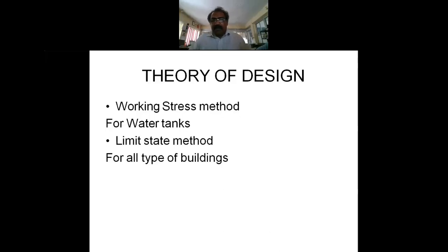Why is working stress suggested for designing water tanks? Because in limit state, we allow the material to strain as much as possible up to the limited deflection, limited crack width or limited yield. So there is a chance that water may penetrate inside the sections. But in working stress, we highly reduce the working stress, and the balance is the reserve, so it does not allow further deformations or even mild cracks. So it is an uncracked section. Working stress means uncracked sections.